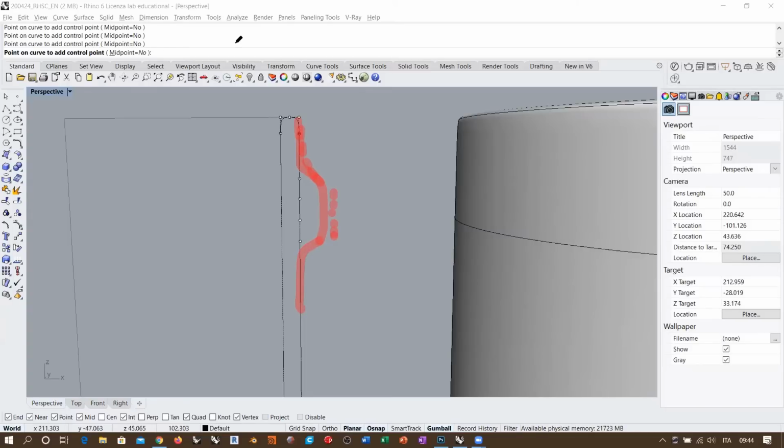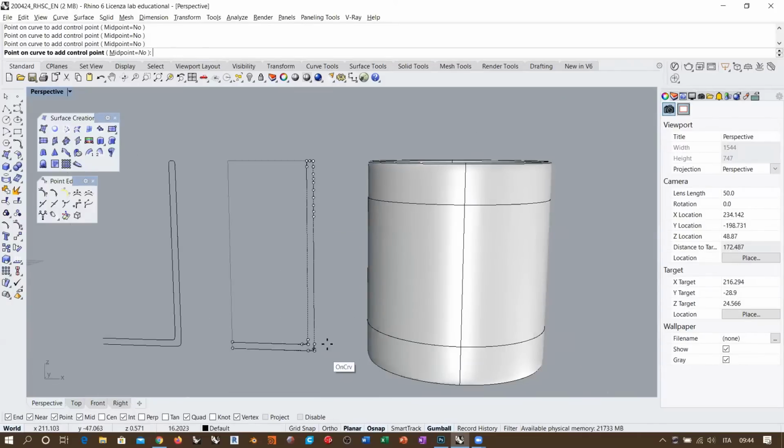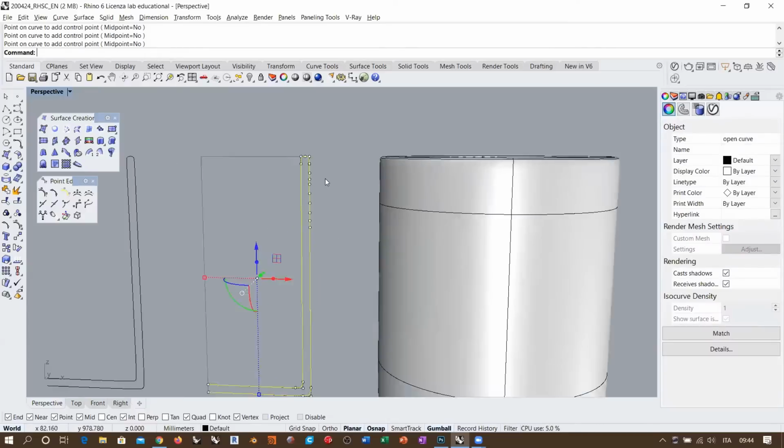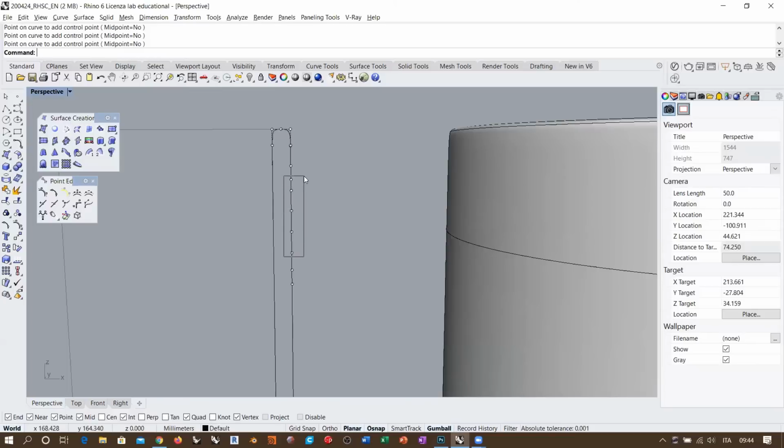So I need more control points, basically. Okay, so if I need more control points, I need them in this area to go flat before reaching the top of the glass. So I will place eventually, you see that I have 2 control points here. So I need another couple of control points in order to maintain this side flat. And so I will take, for example, 1 and 2 here. And then I need also 1 here and another 1. Because at the bottom, I already have other 2. Okay, and that's it. Now I will leave these 2 untouched, and I will select these 4 control points.